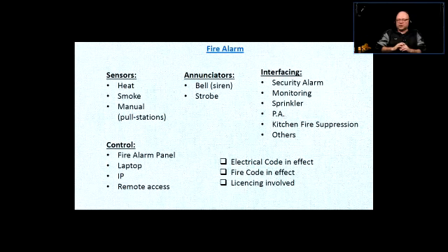And sometimes there's a separate speaker system, a separate audio distribution system, and sometimes the annunciating modules would have the noisemaker. I call it a noisemaker, or sounding alarm, or it could also be associated with a strobe light. And third one, there could be a speaker, a PA speaker, as part of that annunciating module.